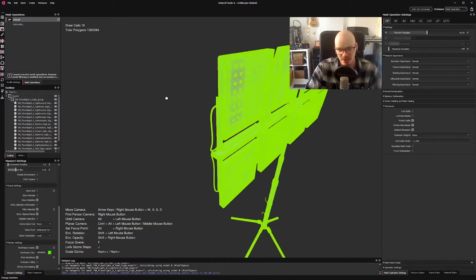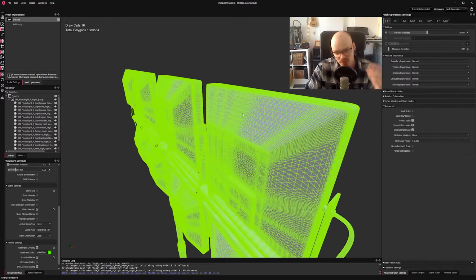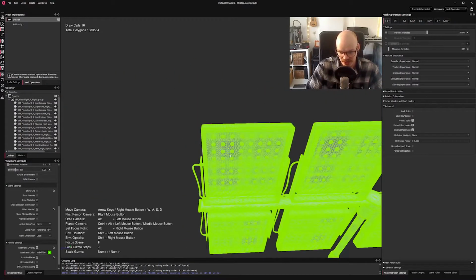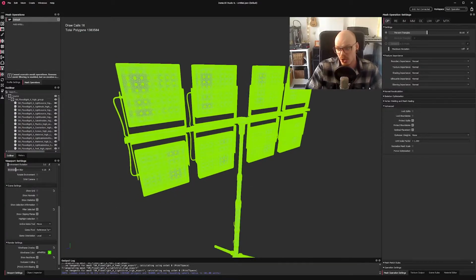And then we've got all of these other flat surfaces on the back. Again, what we want is the flat surfaces to just be made up of a few triangles and then some more triangles along the curvature so that those bevels and details are maintained. But everything else can just be removed because it's unnecessary. So again, optimizing to a specific percentage isn't going to work. It's just not going to be enough.